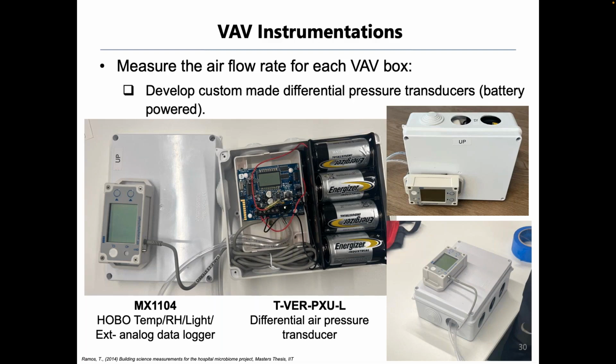At that time, I think the platform was new, so we ended up using the equations in the data sheet for, I believe it was a linear relationship between pressure and voltage. So we manually used the 0 to 5 to translate the voltage to differential pressure. That was how the differential pressure was captured. So we got the delta P.